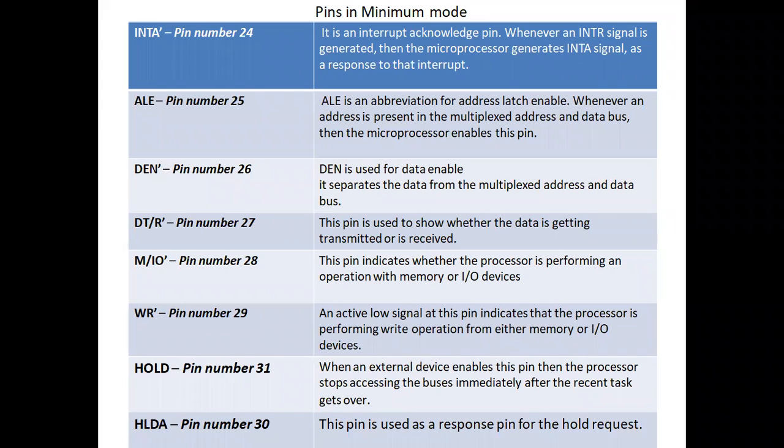Now next is the HOLD pin. Whenever an external device enables this pin, the processor stops using the buses immediately, and holding is done until the external task is over. I will give one example.